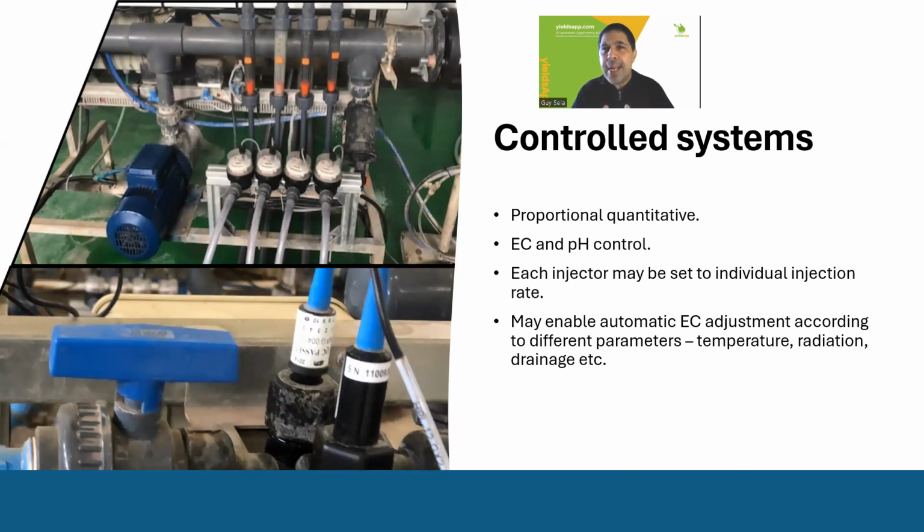But it's all related. It's the crop nutrient requirements, it's your water quality, it's your soil quality and composition, okay? And then for precision fertigation, of course, you need the EC and pH on the system. Highly recommended to have flow meters.